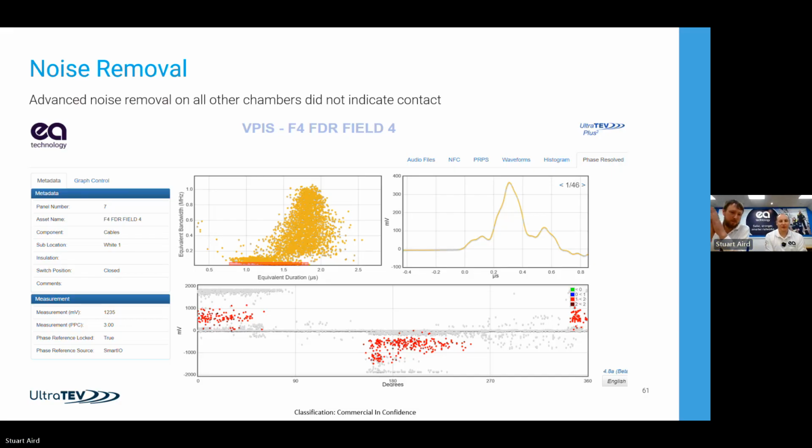So, nice cable termination. You'll see evidence of PD activity on the outside of that. Jot down a number next to yourselves. Have a quick look. How many different sources of PD can you see? There's a few, so I'll let you count. Okay, well, full marks for anybody who got 14, and they're the visible ones from this angle.